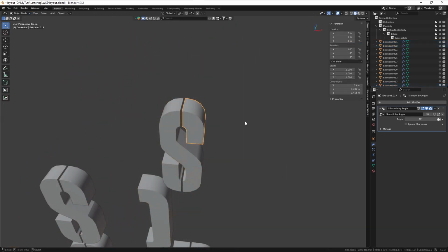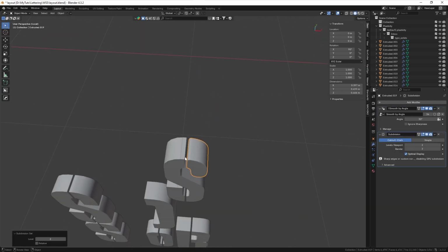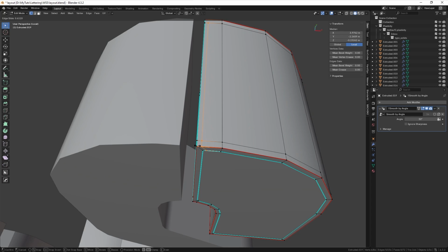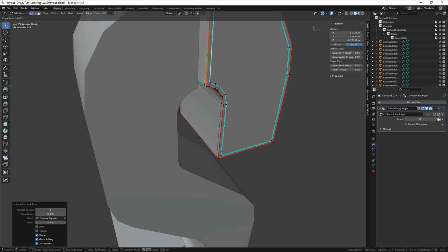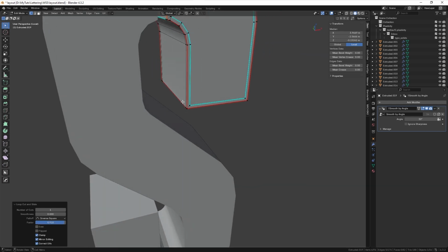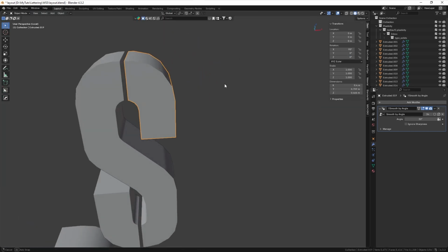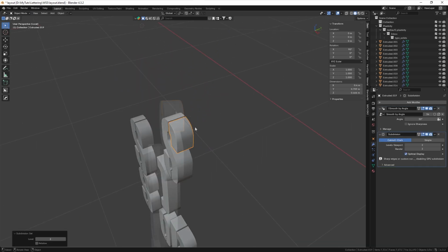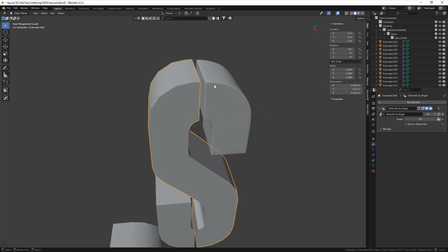But we aren't ready with our tightening. If we run the SubDiv modifier right away, pressing Ctrl 2, you see this part is flat, but here the edges, they are collapsing. So that's why we need to add some edge loops also here at the corners, simply by pressing Ctrl R and repeat the process for all the corners for avoiding them to collapse when running the SubDiv modifier. So now again, let's run the SubDiv, pressing Ctrl 2, and that's what we have. That's what I want to have. Smooth, rounded shape. And I will do the same for all the other parts.